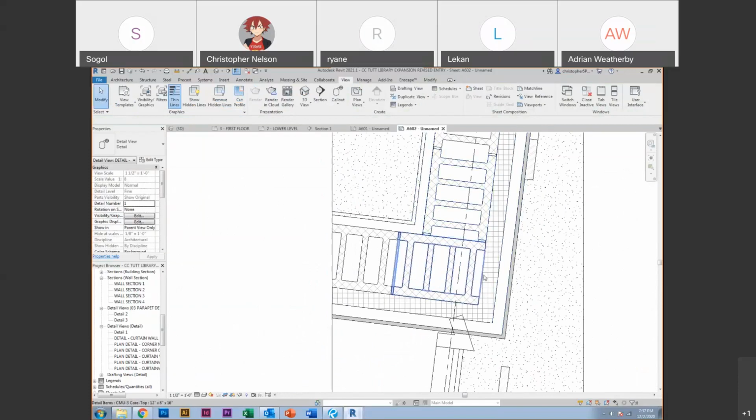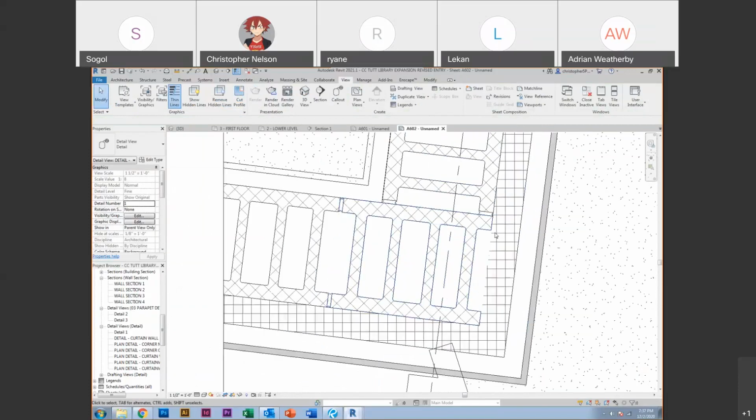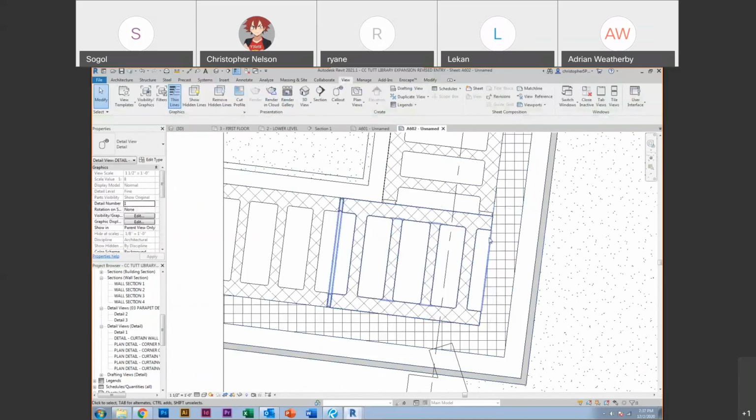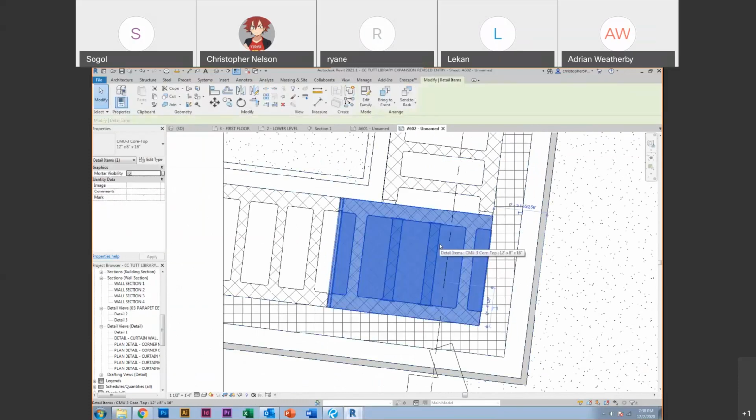So, I have my masonry. Just know in real life, they're gonna grout. They're gonna find like a solid grout kind of corner, and they're gonna grout this kind of empty full, so you don't have an empty corner because that's just weird. Lots of times they're gonna have steel in the corner, obviously, so that's gonna help you kill your corners most times.